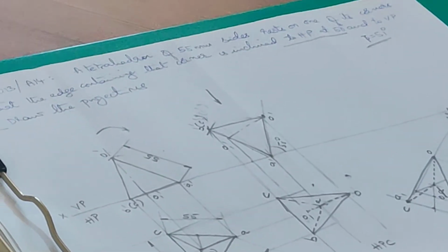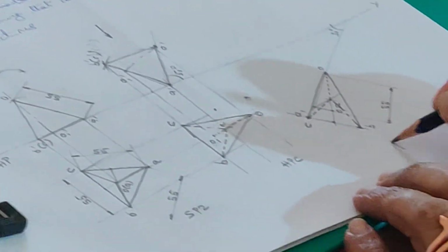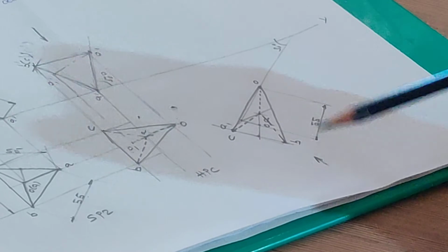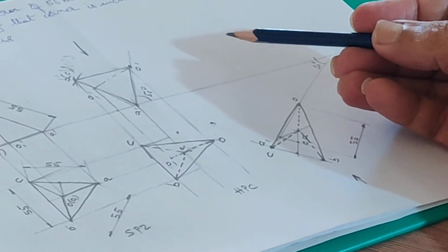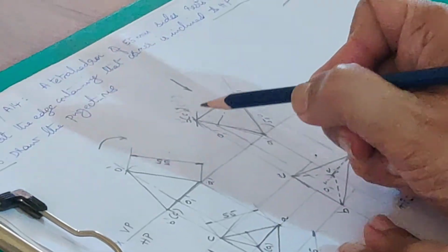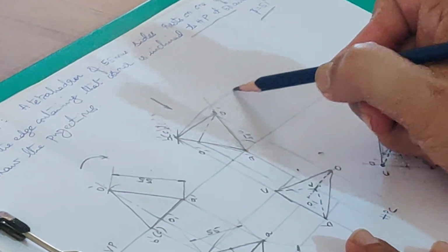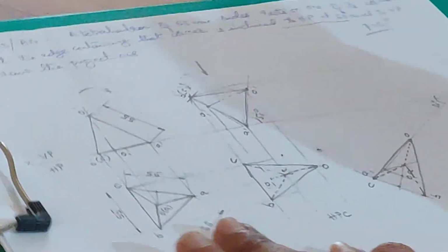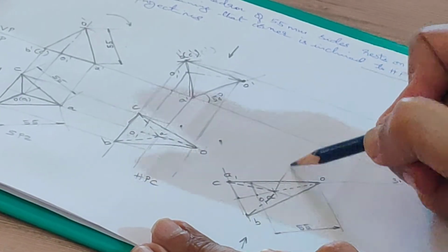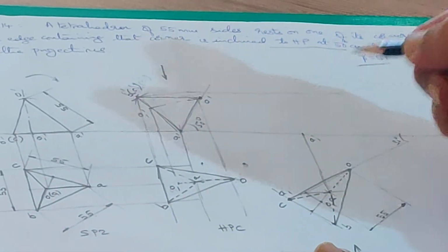Now let us move to the front view. This is the position of the observer, and this time the base is nearer to the observer, ABC. So when you draw the base in the front view, that should be drawn using solid lines. Now this is the projector passing through B and C, and XY line is the locus for A. So let me project A till here. This should be A dash.